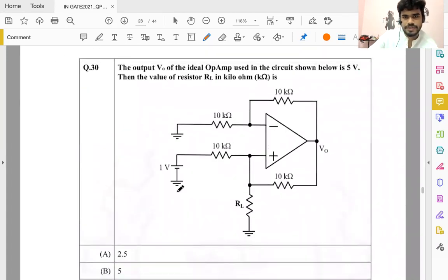Let's get here. Okay, OpAmp we could do. So I had some conversation about this with some of you. Notice there is a positive feedback loop, but the saturation values are not given. And so presumably this is still in the working range. Because unless the saturation values are given for an ideal OpAmp, how do you deal with a comparator? In fact, there are two ideas here.